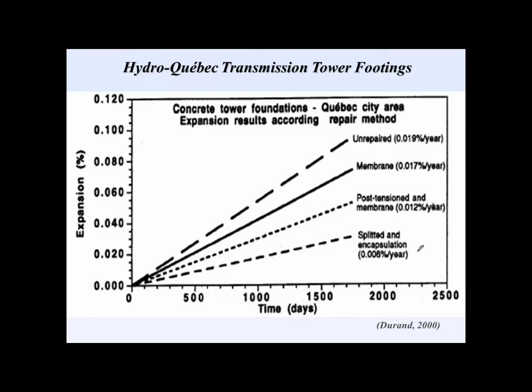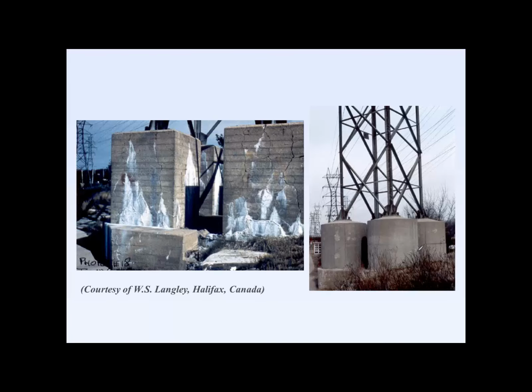One thing I should mention, and perhaps I should have mentioned it at the beginning, is anytime you're dealing with a structure and you're considering applying external restraint to it, our group recommends very strongly that you consult with a structural engineer before any kind of retrofit is done, just to ensure that the structural performance of the structure is not compromised in any way.